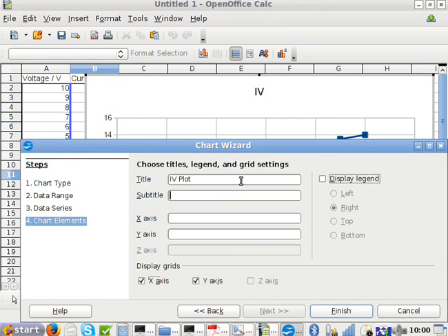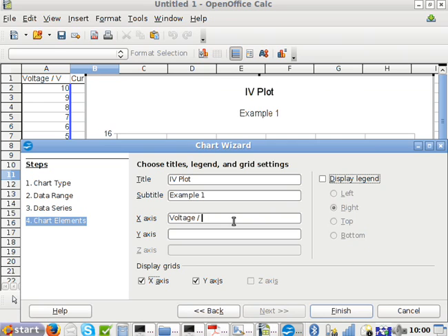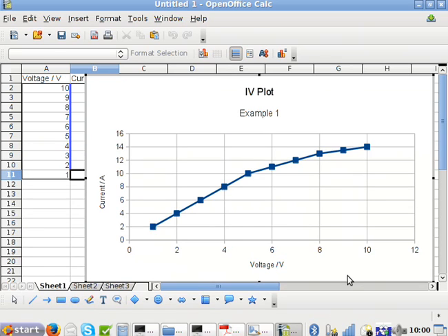Yes, got that? Okay. So now on to Ohm's law. So Ohm's law states, for some materials at a low voltage and a low current and a constant temperature, the IV characteristic graph will be linear, passing through the origin. So look, what type of graph is this? Linear. And will it go through the origin? It will. So this is actually called Ohm's law, that the graph goes through the origin and it's a straight line. That's Ohm's law. Write that down? Yeah.